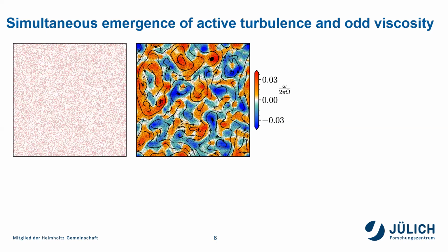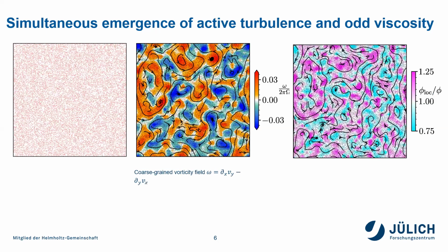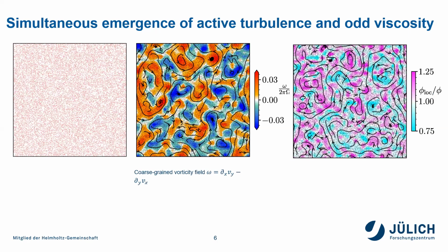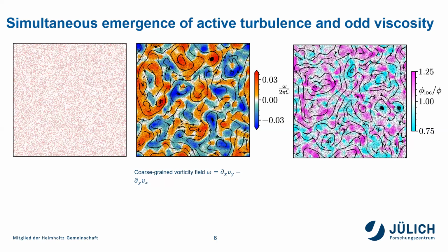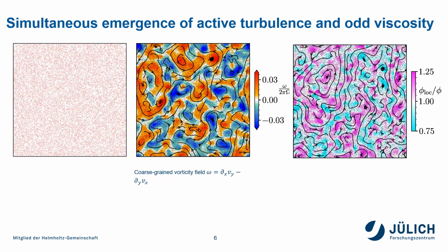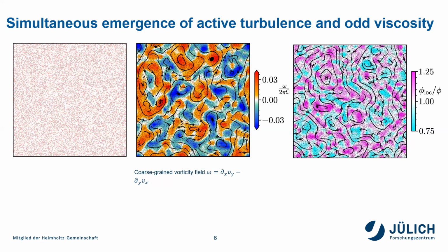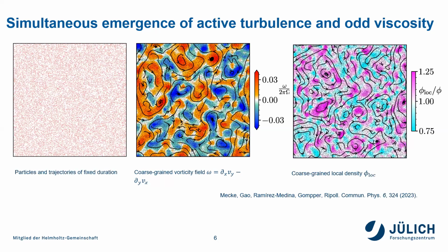Okay. What you have seen here is the vortices forming. If you analyze the vorticity field, what you see is that there are areas of large vorticity, which means that the whole vortex is rotating in the same direction as the rotors, and areas of very low, which is negative vorticity, because if there are two big vortices rotating in the same direction, something needs to adapt in the middle, and then it counter-rotates. So all the rotors individually follow the field, but collectively there are some of them that need to go against it.